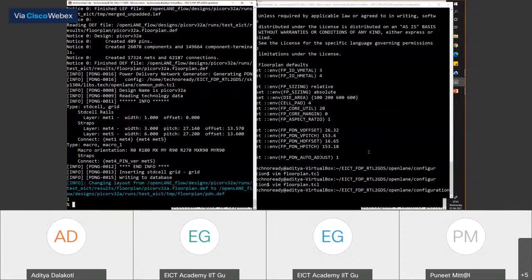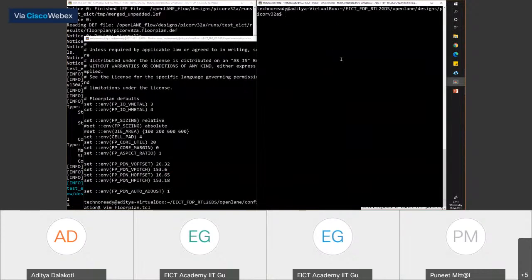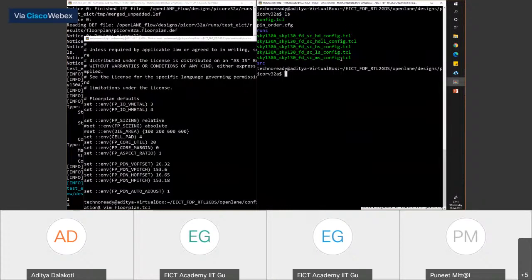So yes, you can obviously change the horizontal and vertical IO layers, and what is going to happen is it will actually change. Again, it is based on your system level: which layers do you decide to route those signals on, based on which layers are available for your block? These are all decisions which you have to make at system level planning.